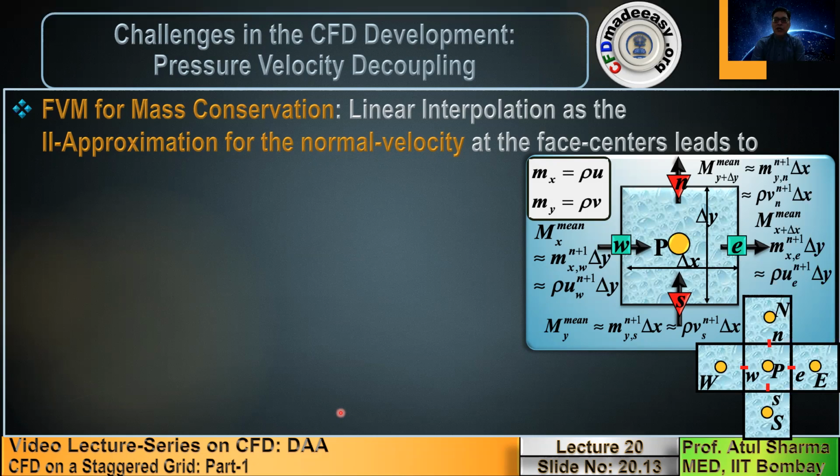But other than this, there are some additional things you encounter when you move from computational heat transfer to computational fluid dynamics as well as heat transfer. For the mass conservation law, you have to use certain approximations which are new to this topic. And second, when you compare the energy equation and the momentum equation, you encounter pressure only in the momentum conservation, not in the energy conservation.